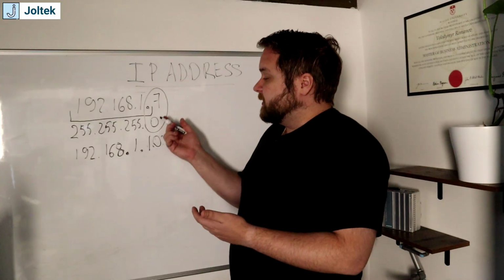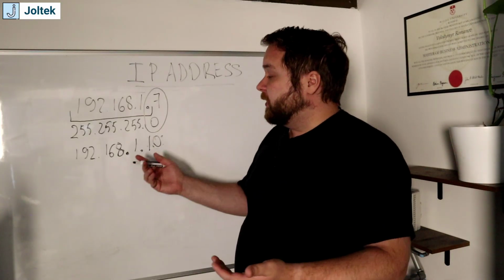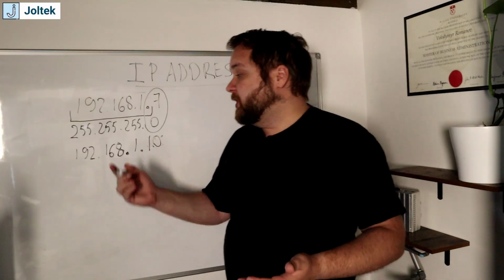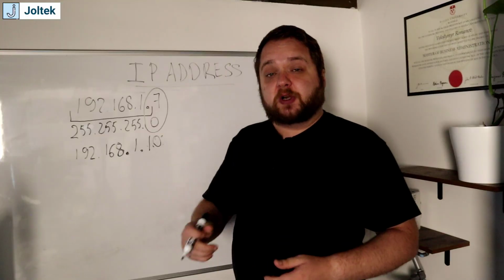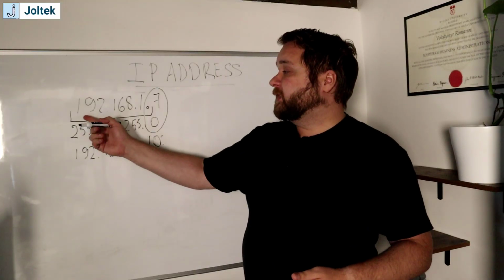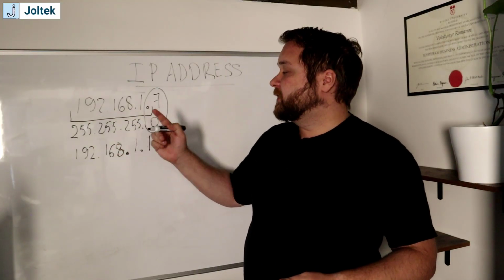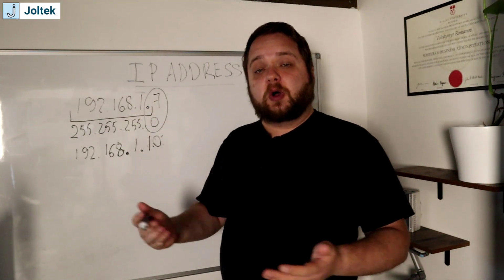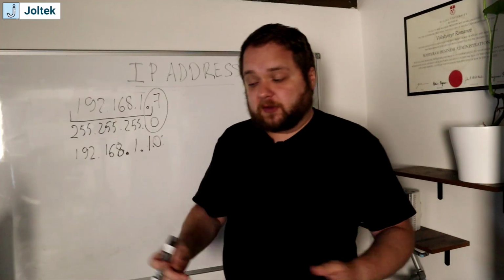So anything that is not 7 would have been allowed to talk between two devices. Similarly, if we wanted to add an HMI and a PLC to talk to that same VFD, we could have selected anything that is 192.168.1.8, for example, .9, .10, so on and so forth, as long as there's no conflicts.